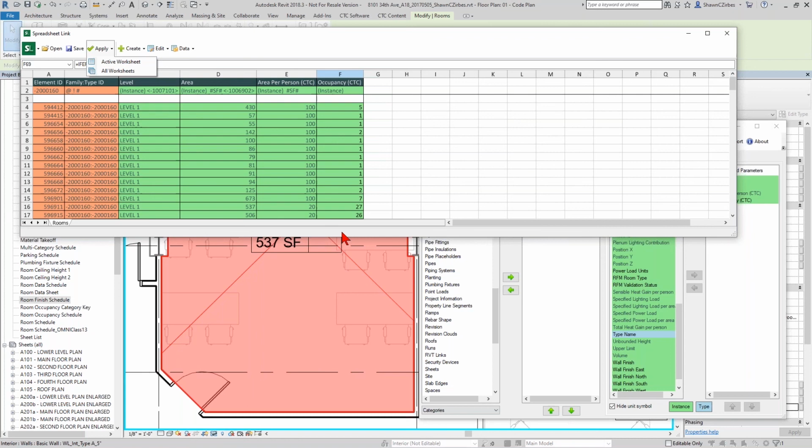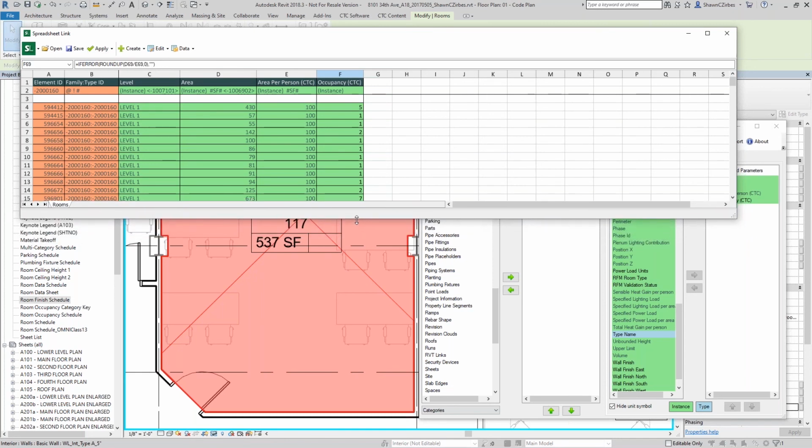But let's go one step further. Because really, this is just occupancy. And rarely do I do occupancy because it's fun, right? I do occupancy because I need to use this to figure out, well, by code, how many water closets do I need to put into my project? How many drinking fountains, labs, how many parking spaces? You name it. How big are my egress sizing?